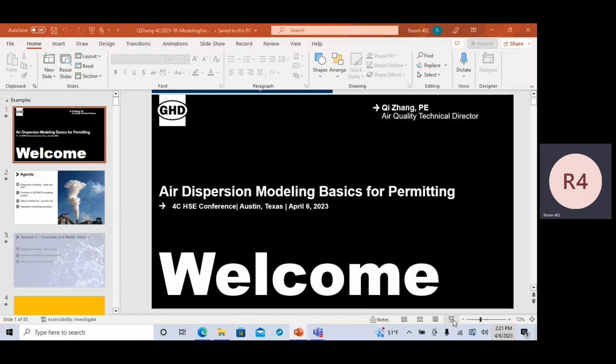Some quick discussion on how to do your AERSURFACE model. You need your study area and location. Put it on your project site. There are some cases where you put it on the met station, but for projects, usually putting it on the project site is more representative. Radius to use: the default radius is 1 kilometer. I did say sometimes you want a special consideration. If the site is very large, more than a mile big, then I would sometimes think about using 3 kilometers.